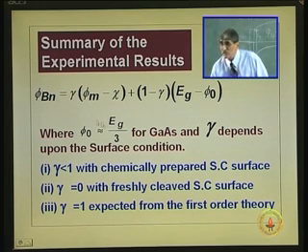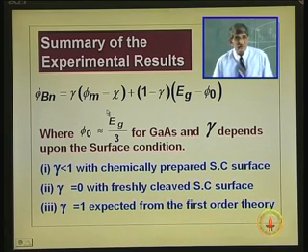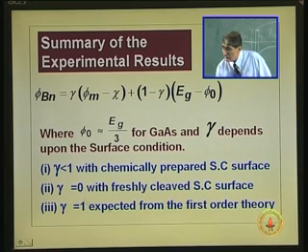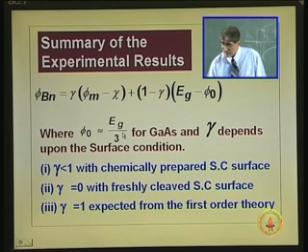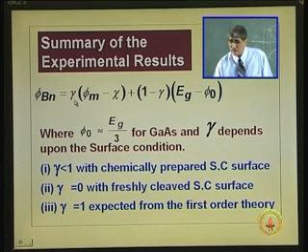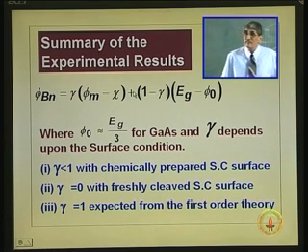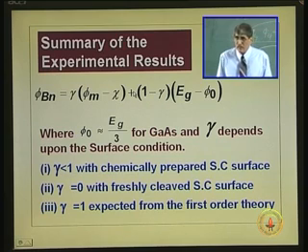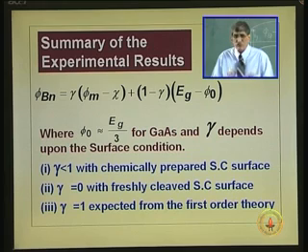And if gamma is equal to 0, that is freshly cleaved surface, gamma is 0. Okay. With ideal surface, gamma equal to 1. Freshly cleaved surface, high density of interface states, gamma is equal to 0. So, if gamma equal to 0, that term is gone, and 1 minus gamma is 1. So, phi b n becomes equal to E g minus phi naught, and E g is fixed for a given semiconductor. That number phi naught, what it is we will see soon, that also is fixed.